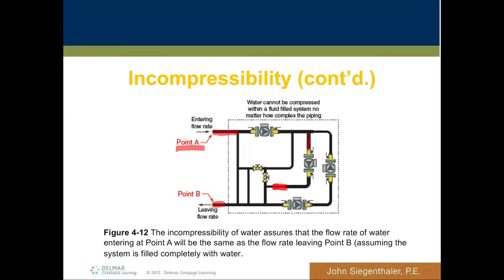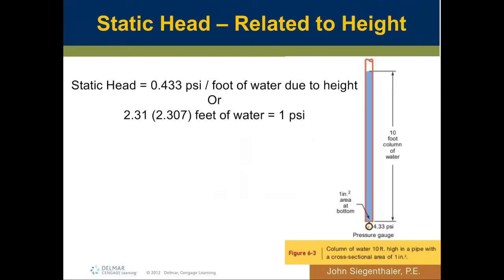And whatever flow rate is going in here is also the flow rate going in here. Essentially, that tells me that anywhere within a single circuit that is common to multiple circuits, I can identify what that flow rate is no matter where I am within that circuit. Whether I do it on the return or the supply, it really won't matter.